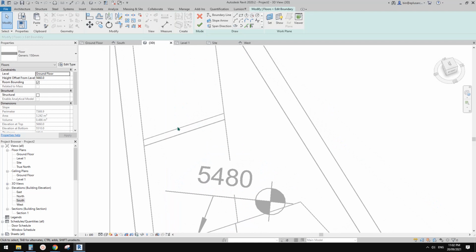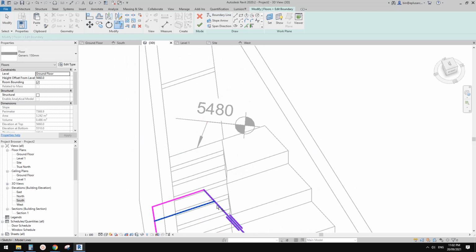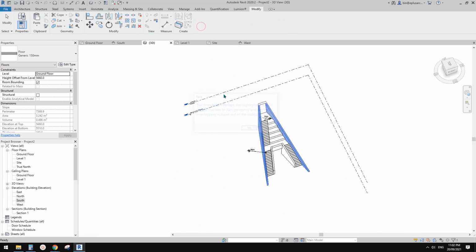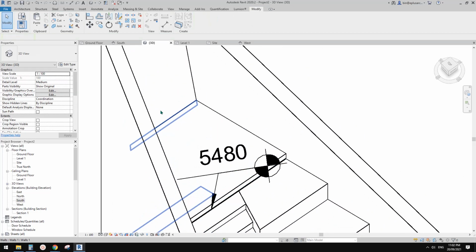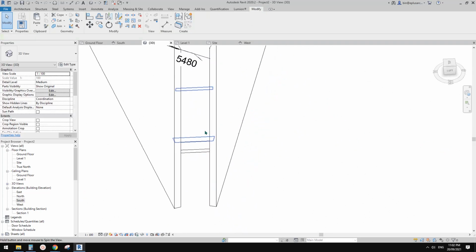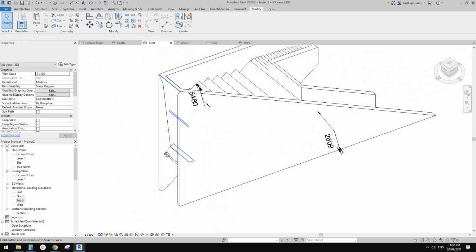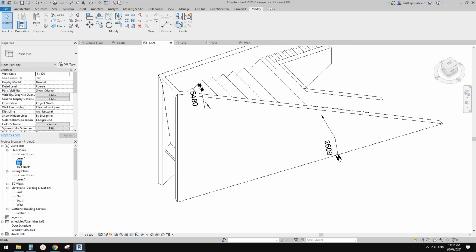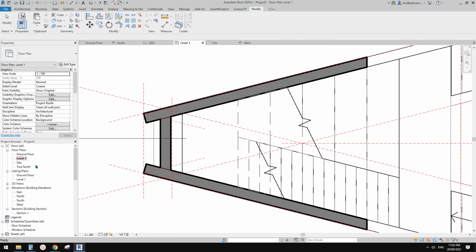So you will be able to pick this line on this wall. So pick this line and then trim it. So now you will have a floor exactly matching this wall. Okay, so stop at this face. So yeah, that's it. And then okay, so what's next? So next, let's go to side plan. Maybe level 1.